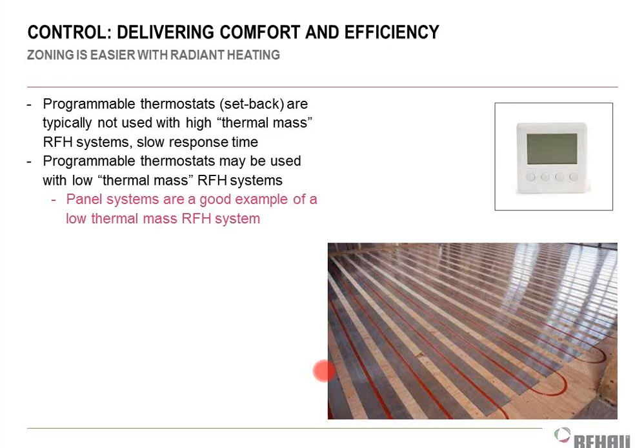Because heat goes from the hot thing to the cold thing, and it moves faster as the delta T is larger. So 62 to, let's say, 10 degrees outside, or 69 to 10 degrees outside, my house will lose the heat faster than Matt's house, right? That's how that's going to work. So I already get the energy saving benefits of just having a radiant system, so not needing the programmable stat to get me the benefits of energy savings.